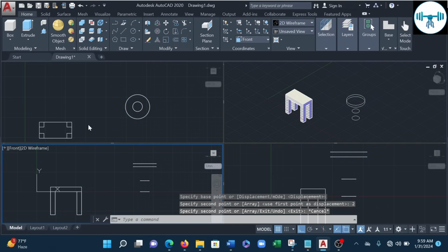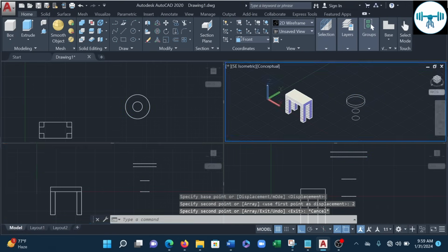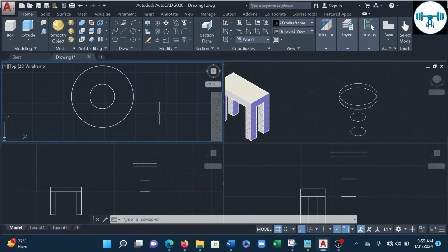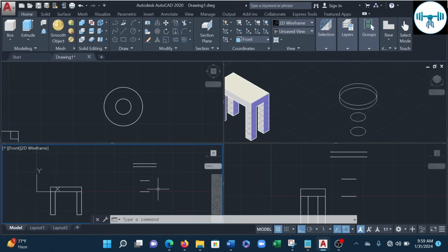Now we look at all the viewports. Okay, so our profile is ready. So we can loft. I'm going to loft either on the front view, the right view, or the isometric, because that's where we are seeing all 4 circles. We definitely can't loft from the top view because we are not seeing all the 4 circles, because we are going to be picking them one by one.